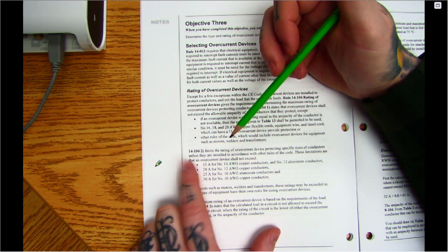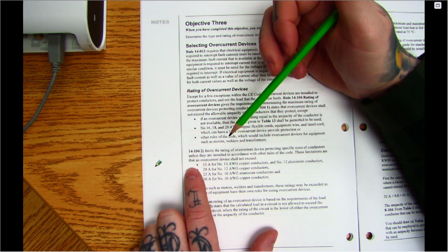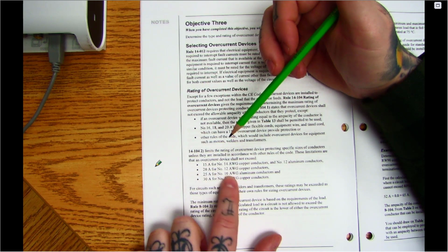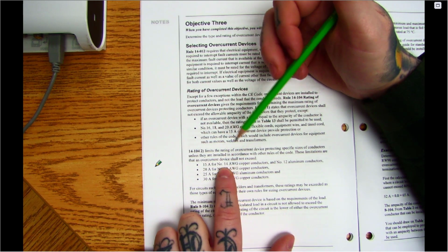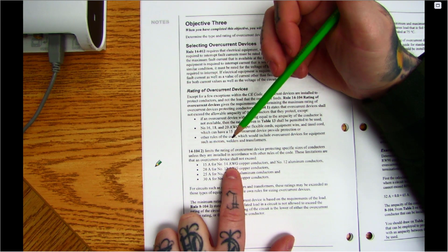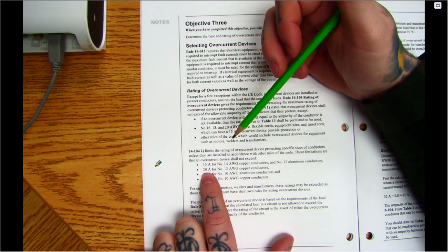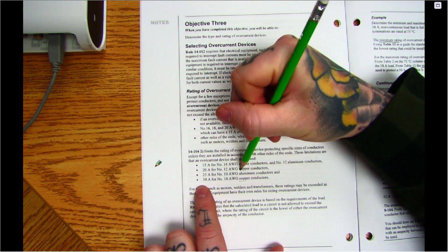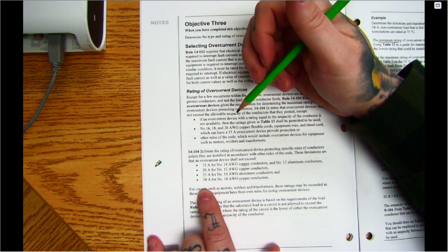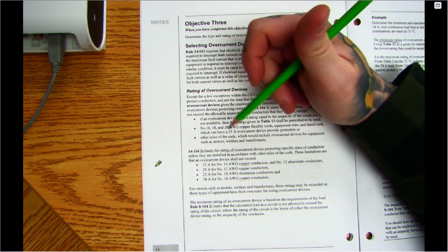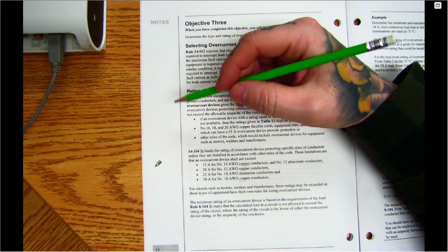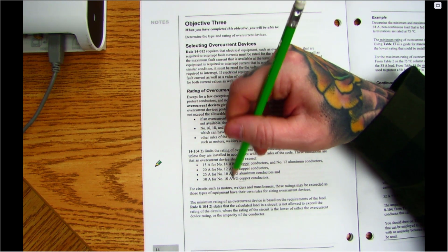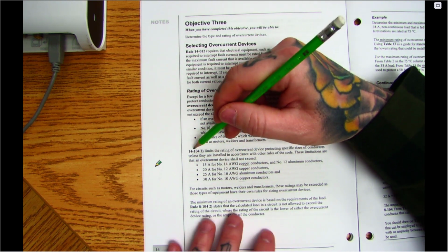But in general, we have to adhere to this rule here, where it's basically saying I can only put a 15 amp on a number, again, we'll talk about copper, a 14 gauge wire can only go on a 15, a 12 can go on a 20, and a 10 can go on a 30. Again, that's copper. There is aluminum as well too. Okay, but those are maximum. So even if we get to a calculated value, and because these wires are rated for higher current than that, this rule says we cannot put them on a larger breaker than that.